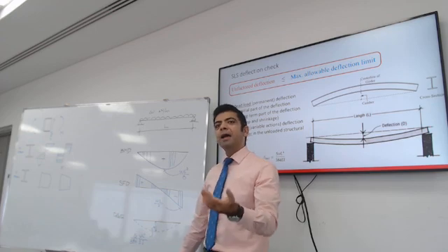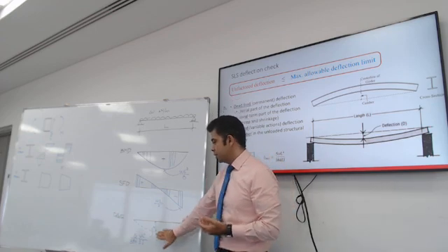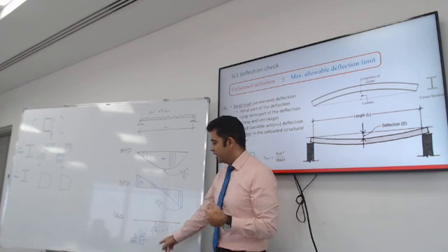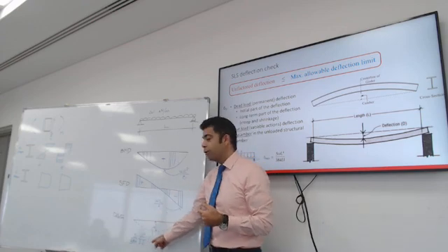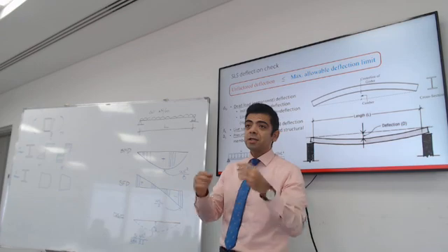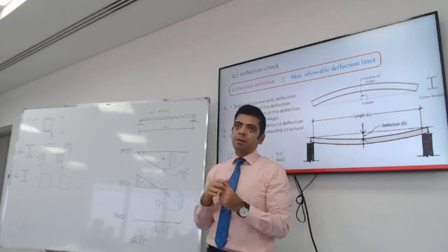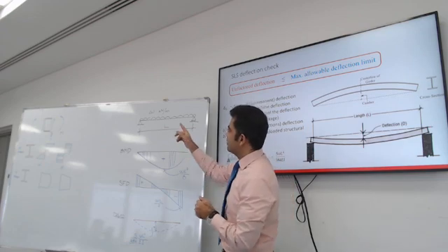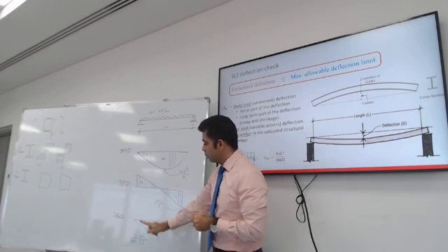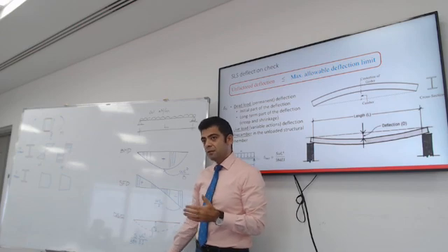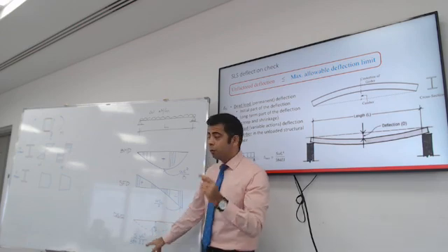As a matter of fact, just a couple weeks ago, we introduced the deflection formulas. If you go back, you will find that this formula over here is the maximum deflection for a simply supported beam with a distributed load at top. So if this had a point load, you would have to use a different formula. Does that make sense? So this formula only works for this beam.